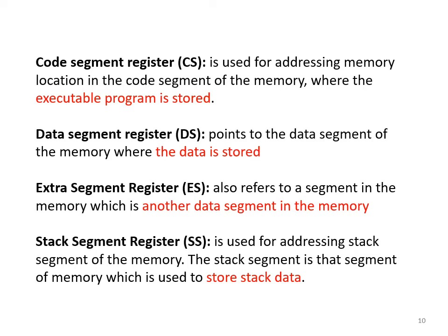It is like you have to store that address or that instruction. What is the address of the next instruction you are supposed to execute once you come back from the execution of that subroutine? So that will be saved in the stack. So, the address of the next instruction after the call, for example, say call add numbers. Add numbers is the subroutine.